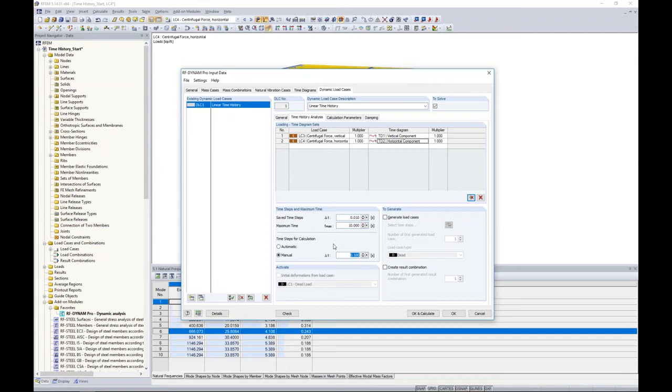So way back in the PowerPoint, I had mentioned a suggestion of a time step equal to or less than 1/20 times our frequency. Now remember, the frequency is the largest frequency from either the excitation or my natural vibration analysis. In our case, this was exactly the same at around 25.8. So this comes out to about 0.001 seconds.